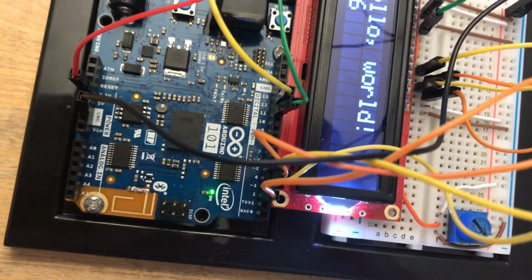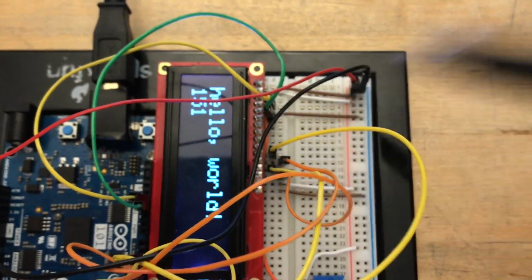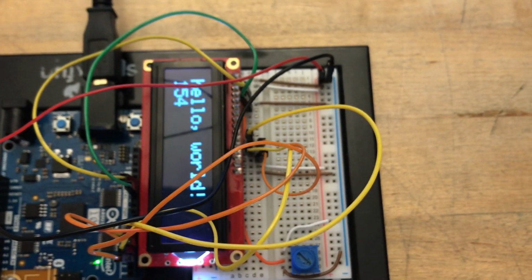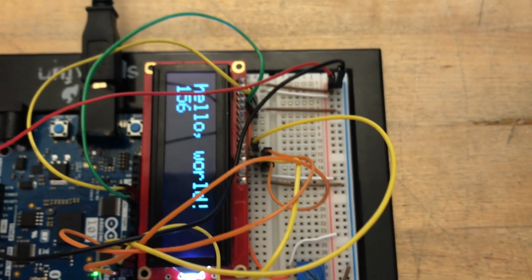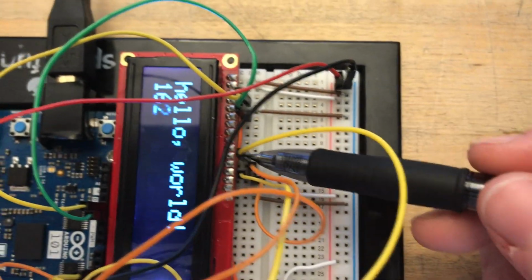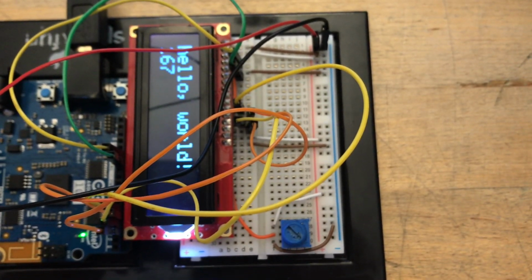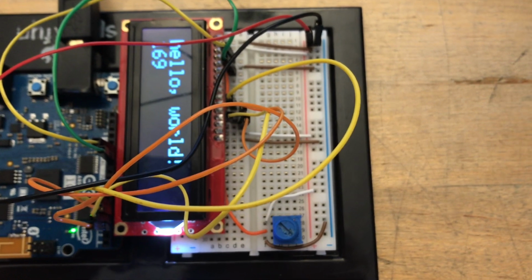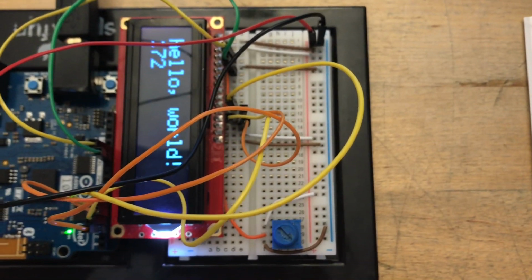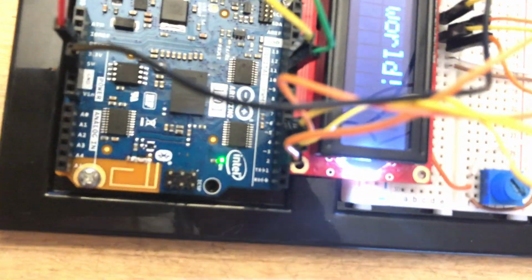So that's connected to pin number 11 on the Arduino board, and the yellow wire is connected to pin number 12. Then we're going to skip the next 4 or 5 pins here, and those are just data bus bits 0 to 3. Then we get to this yellow wire here, which is pin 11 on the LCD board, and that's DB4, data bus bit number 4, and that connects the board to pin number 5 on the Arduino.